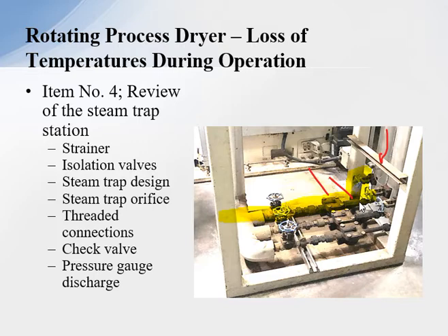The other thing on rotating dryers that we'd like to do is come off and bypass around the steam trap with a needle valve and come back into the condensate return system so we get some blow-through steam, which assists in the evacuation of a rotating dryer. The other thing on the system is that during operation there are steam leaks from the threaded connections, and we want to eliminate threaded connections as much as possible, or totally.